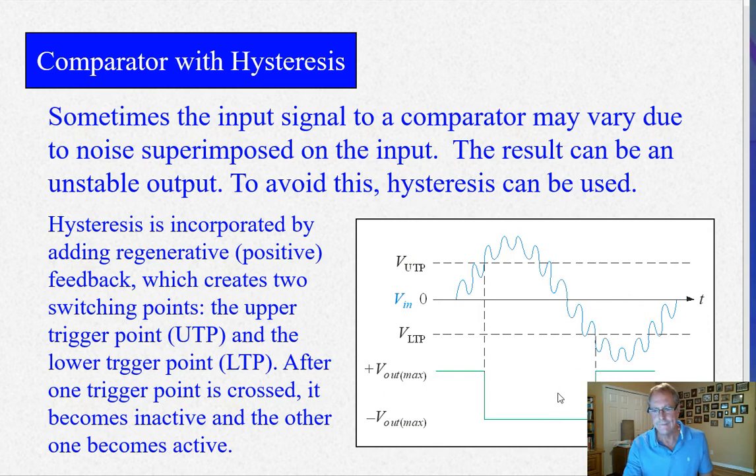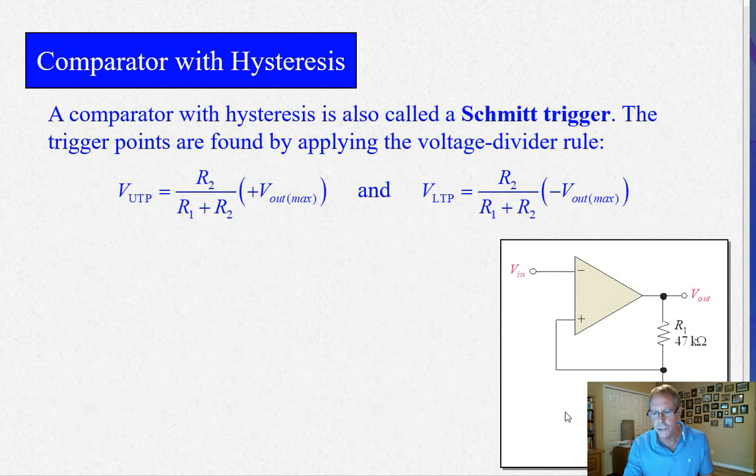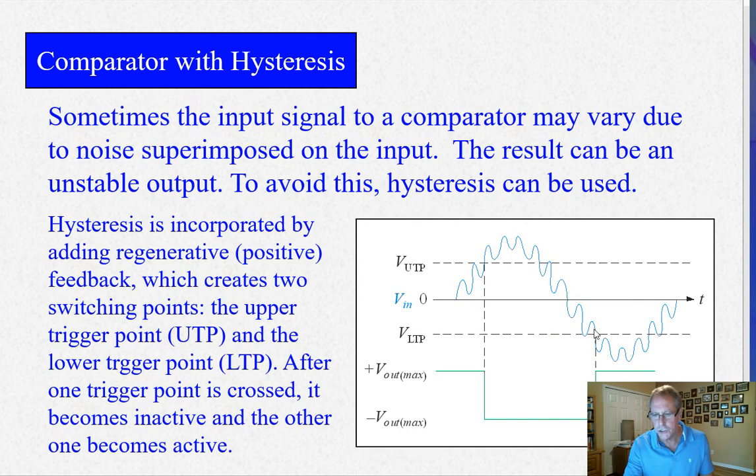And here we are, if we didn't have hysteresis, which we'll talk about in a minute, what would happen right here at this 0 crossing is you might get a little chattering, okay? A little chattering right here on the output. In other words, it's going to switch high, low for a little bit while this wobbles back and forth. It doesn't show that it's going back and forth up and down across 0, but if this noise was a little higher, it would definitely do that.